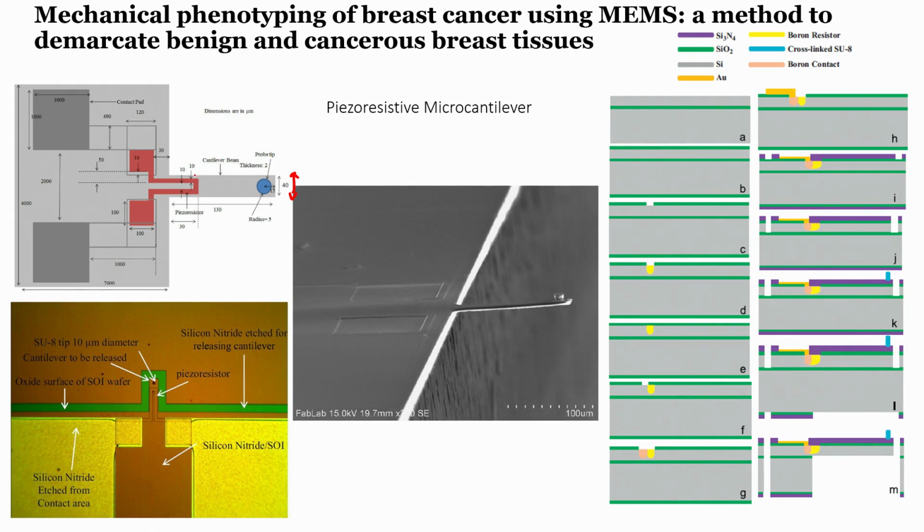For the piezoresistor, the width is 10 microns, and the spacing between two piezoresistive lines is 10 microns. The spacing between two contact pads is about 2000 microns. The overall chip size is about 4000 microns, which is 4 millimeters. The piezoresistor length from the contact pad to the end of the piezoresistor would be 60, but from the silicon wafer edge to here is 30. You see here is 30 and then another 30 is 60.